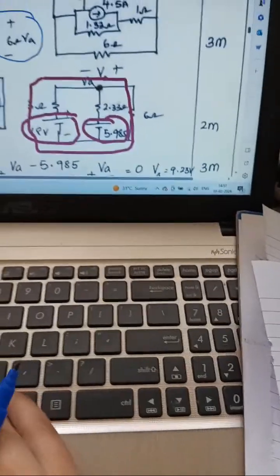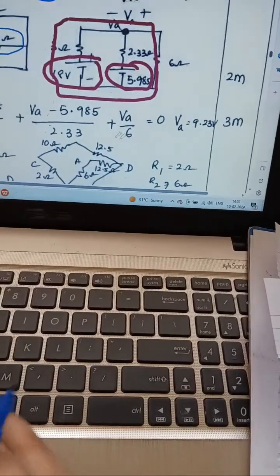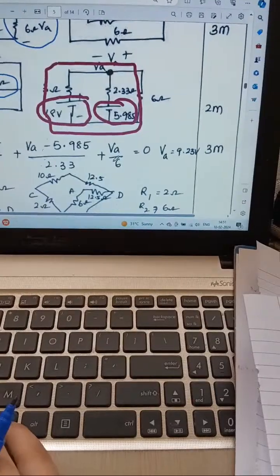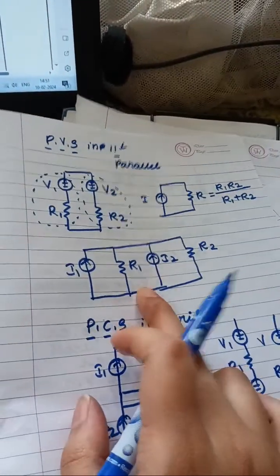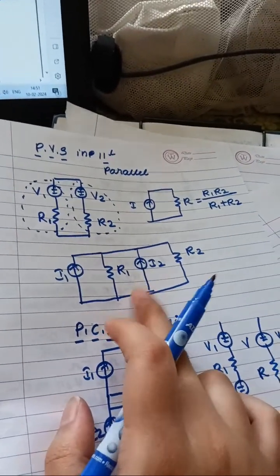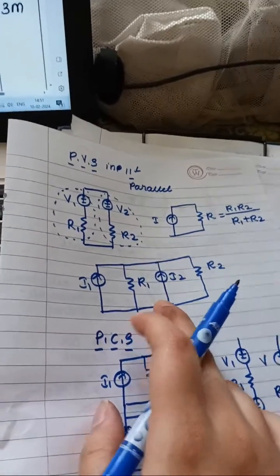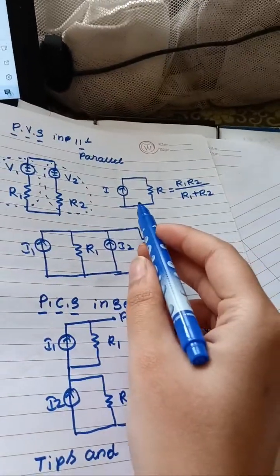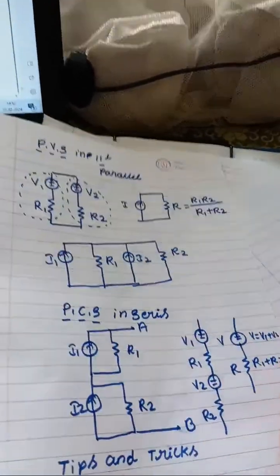So for this, you have to simplify using this procedure. They have used nodal analysis. You can use whatever methodology you require. For example, I told you how we simplified the practical voltage sources in parallel like this. So you can use this methodology. This methodology is the easiest one, students. Don't go to nodal analysis and all. Do this process only, whatever I have taught you. If you simplify this one, you get it into this one, and once again you can use the methodology at the end.